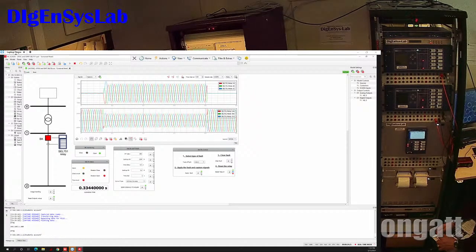Okay, right now we have a trip. But if you see, the timing is different. Maybe you cannot see so much difference between the times because it is the same fault, but if we select another time dial, we could see another time. Okay, that could be an option. Let me change the time dial to show them that the thing is properly working, okay?